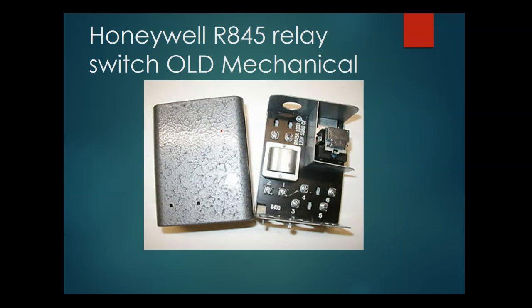This is the old relay. Again, it's mechanical, and there's a 1 and 2. 1 is hot, 2 is neutral. These here will connect to the aquastat, and 2 will connect. Well, I'll show you the connection, but here is the thermostat, and we have a transformer here to operate the thermostat, and this here will connect between the thermostat and the relay to connect between the pump. So this will control the additional pump to circulate hot water when needed.